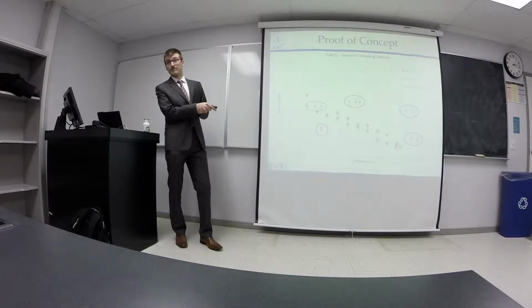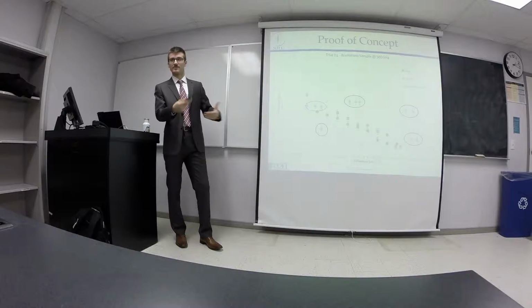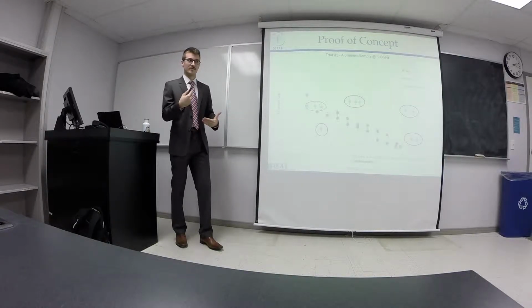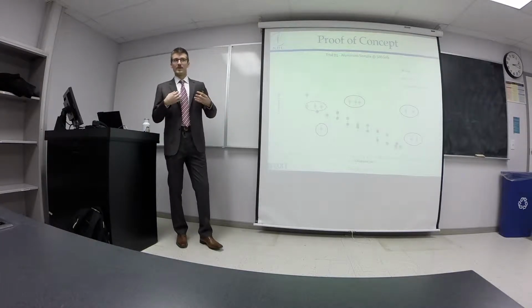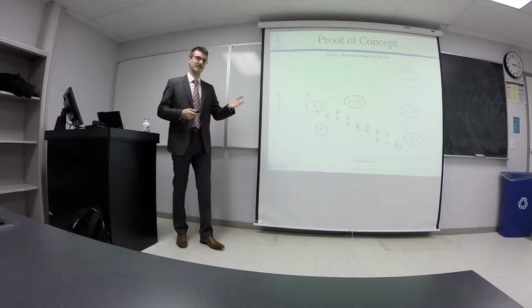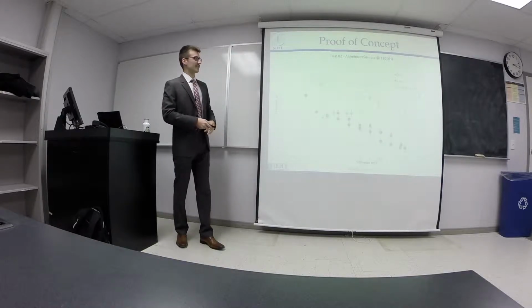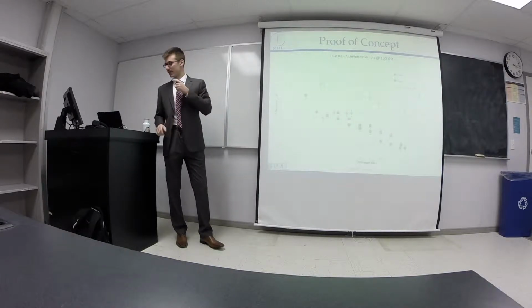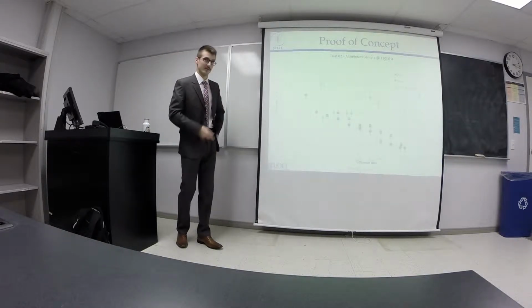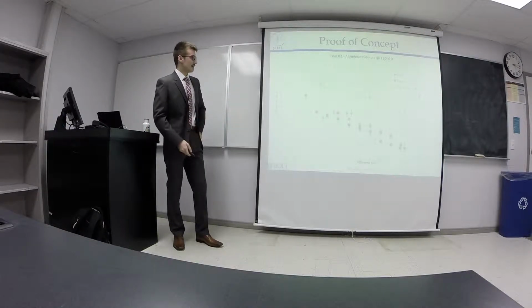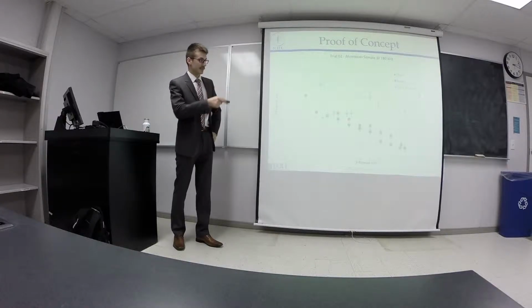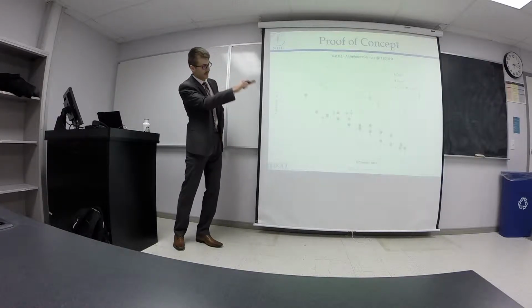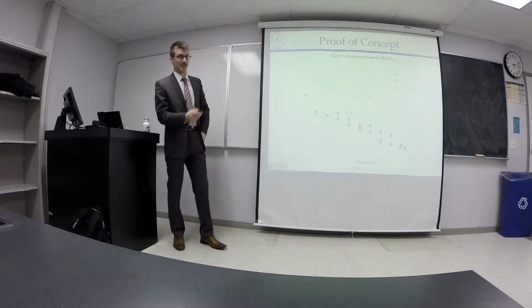You'll also notice that this was at the 500 kilohertz frequency range. So this is just the self-calibrating function that the probe had when you just put it up to a material and it tries to come up with its own detection frequency for a material. But we'll see when I try my actual calculated frequency, we get different results that seem to be a lot more favorable. So you can see we get a nicer, better grouping, and you can see that some of the points that are offset still seem to just follow the same trend as the crack and the flaw.